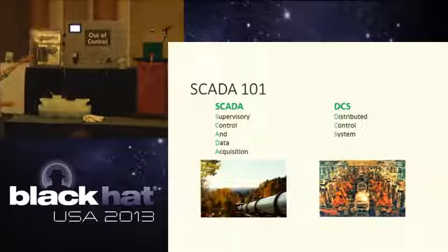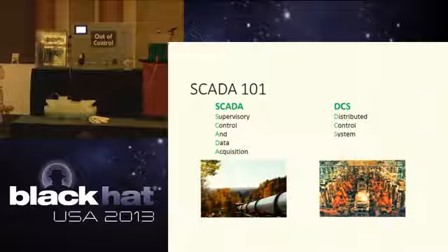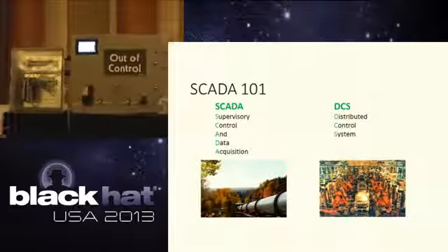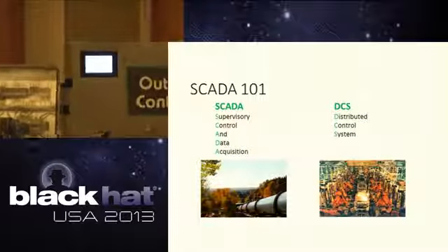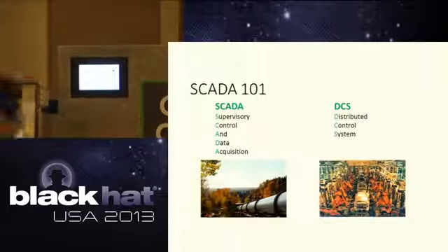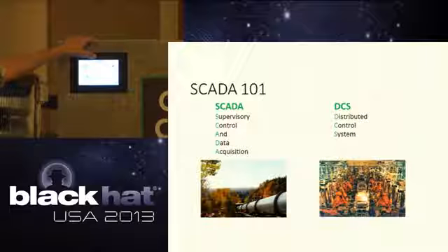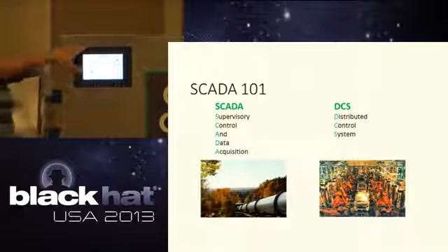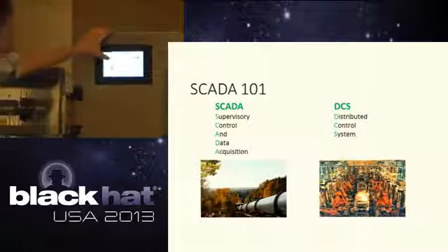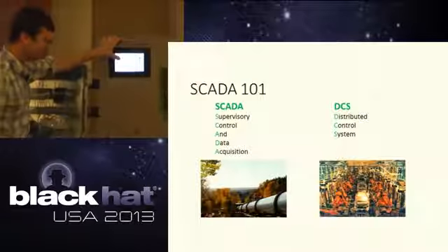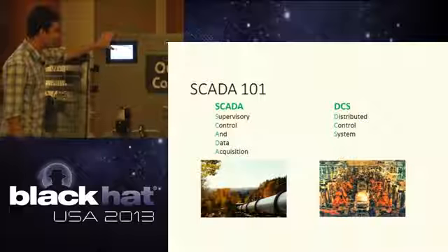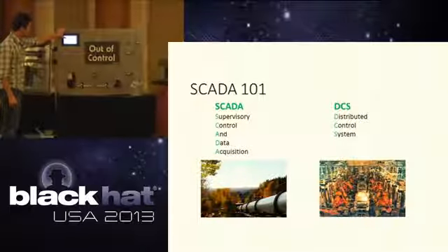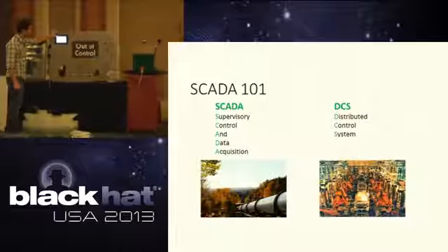One other thing that we have up top is this little screen right here. That screen is called an HMI, and that's the visualization of the process. We can give you a quick show of what it looks like to actually work. All this stuff is touchscreen, and you usually see these installed in the field. The HMI is the operator's view into the process, and it also allows some control. And you typically see alarms pop up on the HMI if any conditions are met.